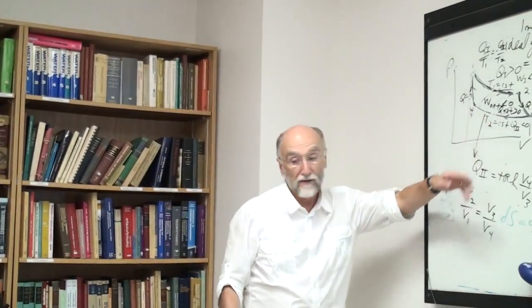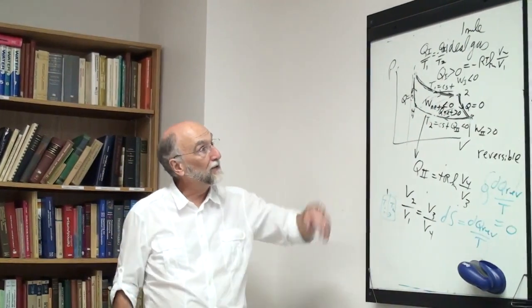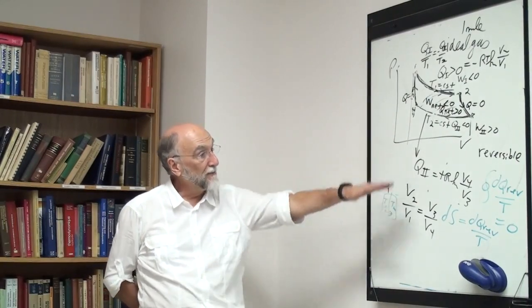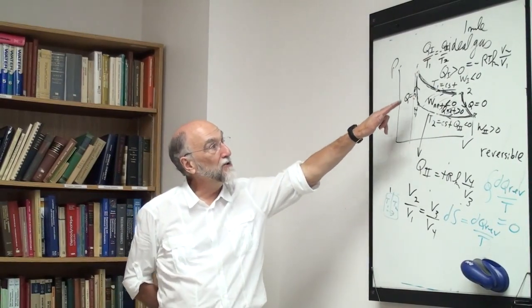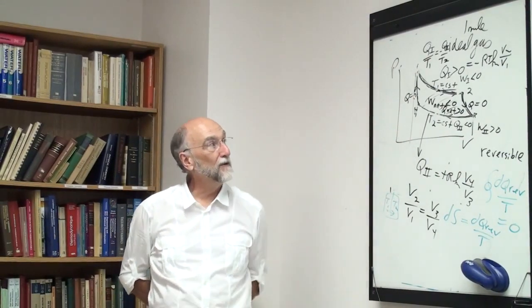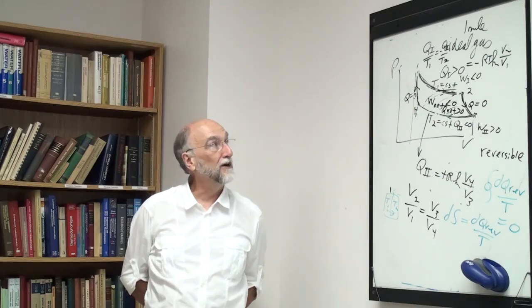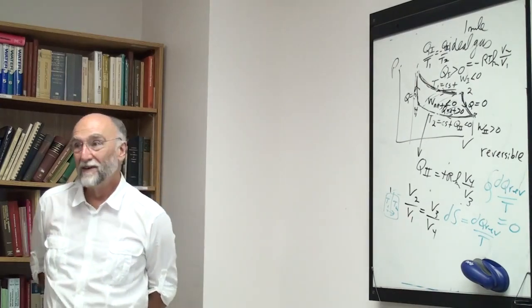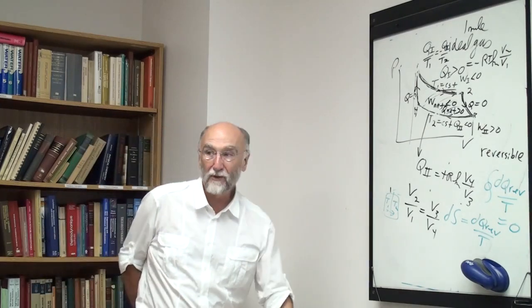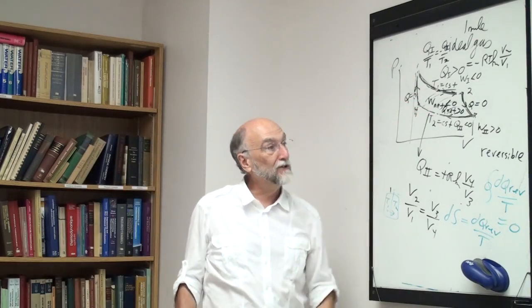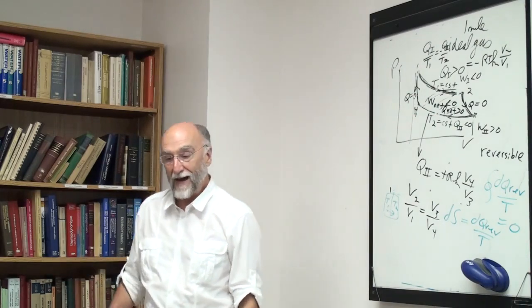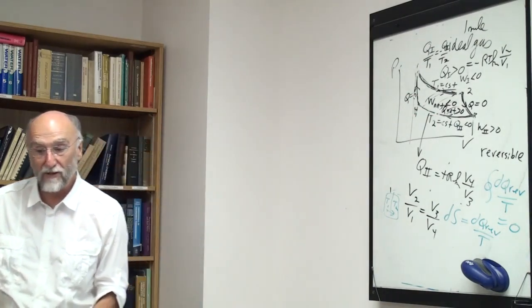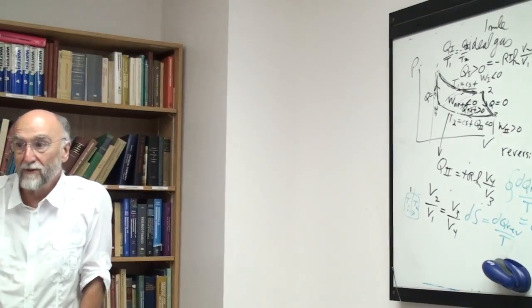We'll talk next time. You can read a little bit about temperature scales. So there is a temperature scale, and in principle then you build a Carnot cycle, and that's your thermometer, and you put that inside the room and you run the Carnot cycle, and that tells you what the temperature of the room is. There's got to be a better way than that. So we talk about the ideal thermodynamic temperature scale and then the actual practical international temperature scale, which we try to make as close as possible.